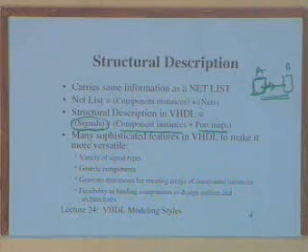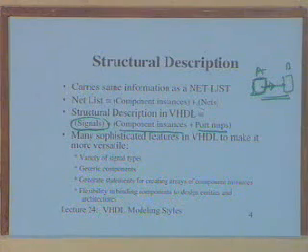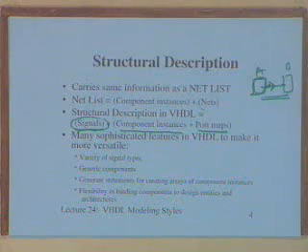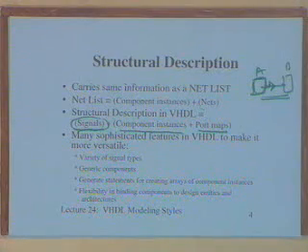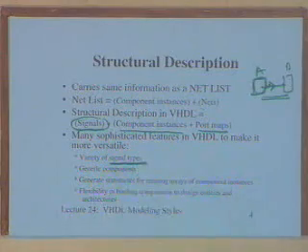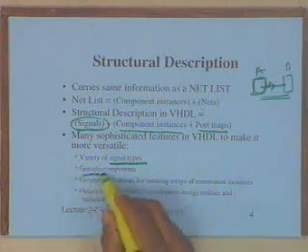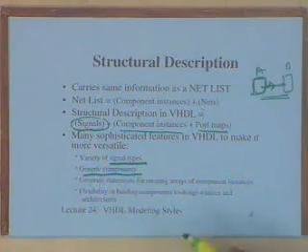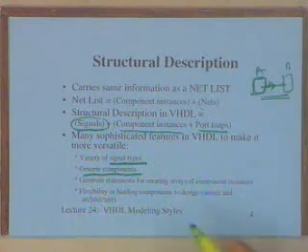Of course, this is a very simple thing, signals, component instances plus port maps, but because we need things like iterative circuits, let's say I can define a generic adder. You need arrays, because when you want to make connections between 16 bits, you do not want to keep on specifying one net at a time. So you require more structured data types, not just bits. A variety of signal types are provided to give you structure. You have generic components so that you can make components which have different sizes.